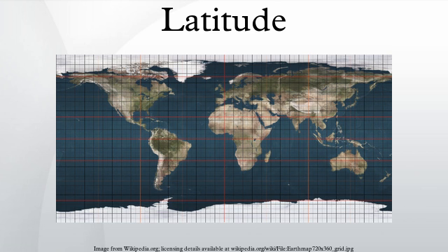The geometry of the ellipsoid. The shape of an ellipsoid of revolution is determined by the shape of the ellipse which is rotated about its minor axis. Two parameters are required. One is invariably the equatorial radius, which is the semi-major axis, a. The other parameter is usually the polar radius or semi-minor axis, b. Or the flattening, f. Or the eccentricity, e. These parameters are not independent, they are related by: